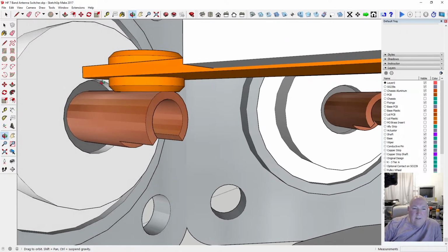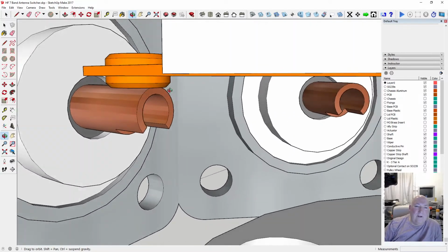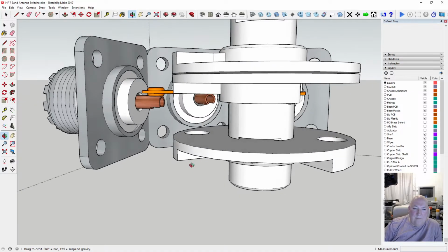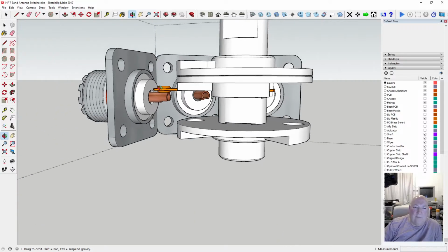So the idea is, because it's round here and this is flat, if you hit it head on there, it'll stall. But if you hit it anywhere from there and above, it should push the spring up and on. And that's what you want, a bit of forced contact. And because of the ball bearings and the holes in the bottom, as you drop it into position, it'll automatically rise, and then when the balls hit the socket, this will drop a tiny bit and touch even better. So we'll try that.